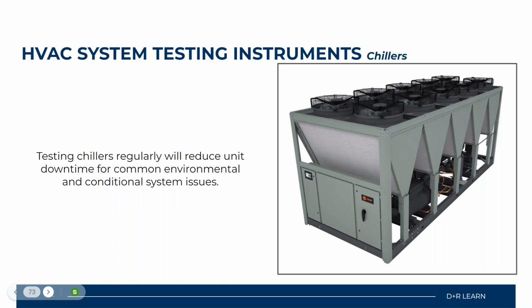Next, we have our system testing instruments for chillers. We just covered boilers, and now we're going to talk about what types of instruments out there are available for testing our chilled water systems. Now, chiller system testing, we're doing this to test for refrigerant leaks and a proper refrigerant charge.